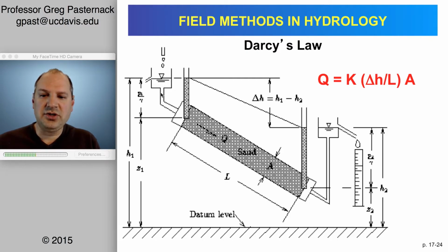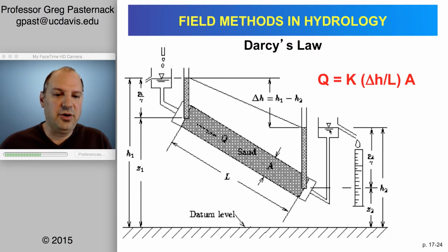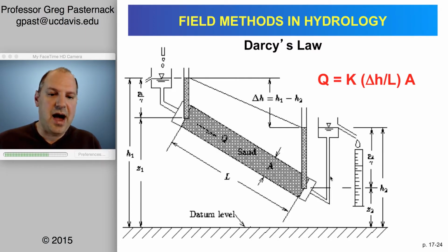And the water is going to be allowed to go down. Now, as water goes down, the water level won't. The water level is going to be maintained by a constant flux that will keep it just at the right level. Similarly, we're going to put another level here that's going to be connected to the bottom. So that creates a hydraulic head at the downstream end. And that is similarly going to be maintained by, in this case, having a spill off so that water will be kept at this level.